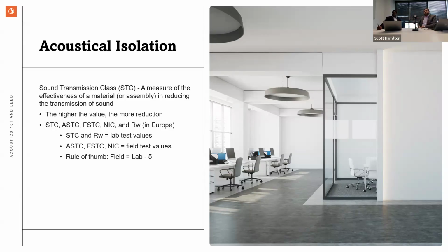It's important to also say that there is no such thing as soundproofing. There is sound reduction, and there are various degrees of sound reduction. There is no magic metamaterial that you put a panel on a wall and suddenly no sound goes through it. It's all about reducing some sound until it reaches a reasonable level that meets all our goals for a project. It's often one of the most disappointing things to a lot of our clients that we talk about: yeah, there's no magic. There's no magic acoustic panel. There are simply STC ratings and the various degrees, and frankly, the various costs that are associated with that.